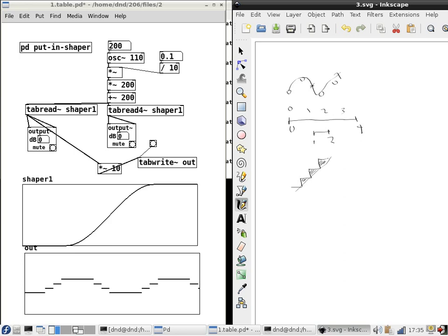And that area is proportional to the derivative, the slope of the thing. If the slope is 0, there's no error, but if there's slope, there is error. And furthermore, if you want this error to be down, say, 96 decibels from the strength of the signal, then that means you want this thing to be 2 to the 16th less in amplitude than the value of the table. And even if you're storing something like a sinusoid, that ends up telling you that you need hundreds of thousands of points in the sinusoid to be able to make this thing actually be audibly good to 16 bits.